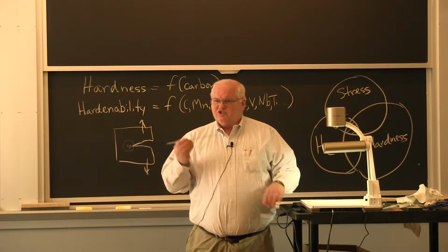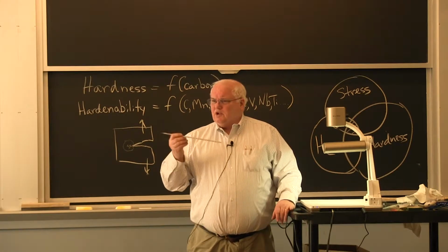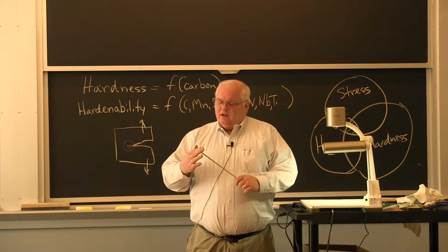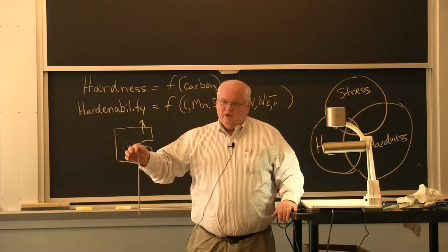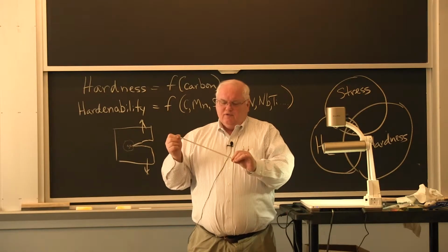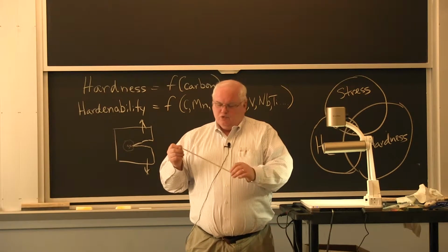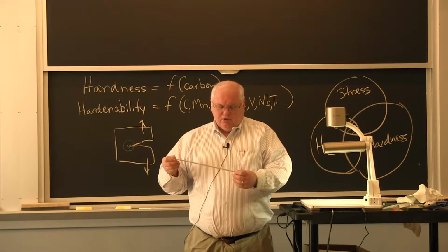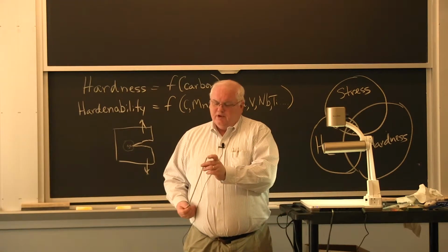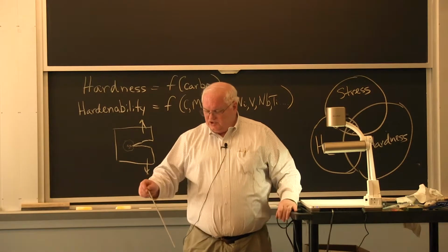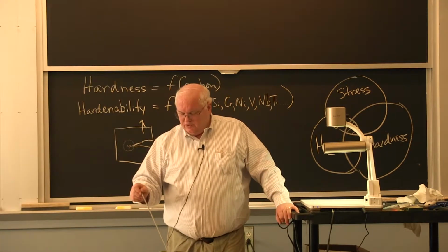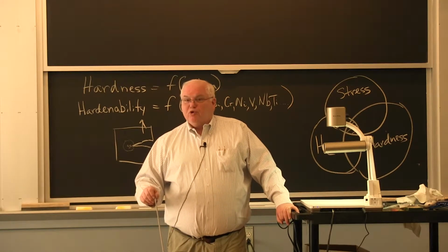Back 40 years ago, 60% of all welding was done with a stick electrode. You take an electrical copper clamp, you clamp the electrode on this end where it has no flux coating, which will melt off and form a slag to pull out the impurities and protect the weld. It has a tip that's been brushed off so that you can strike an arc if you have a helmet on, hopefully, so you don't sunburn your eyes.